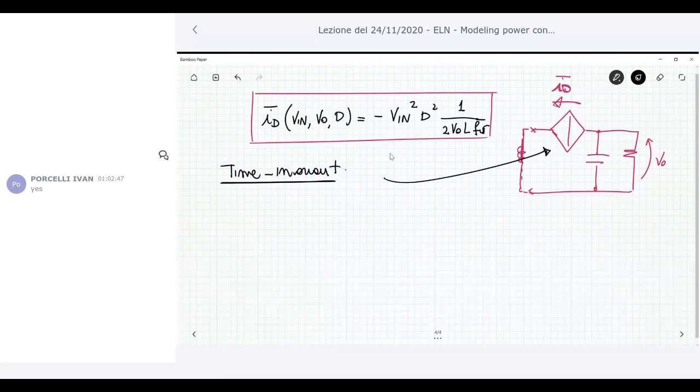So, in which way can we linearize it? Okay, what I described to you up to now is related to the fact that, I don't know, duty cycle is a small signal perturbation, like this one, and V in the same, etc. So I can replace this quantity inside this expression in order to derive the linear transformation of the circuits. And this can be done. Okay, this is a possibility. You have to perturb and then linearize, or you can apply some other methods.